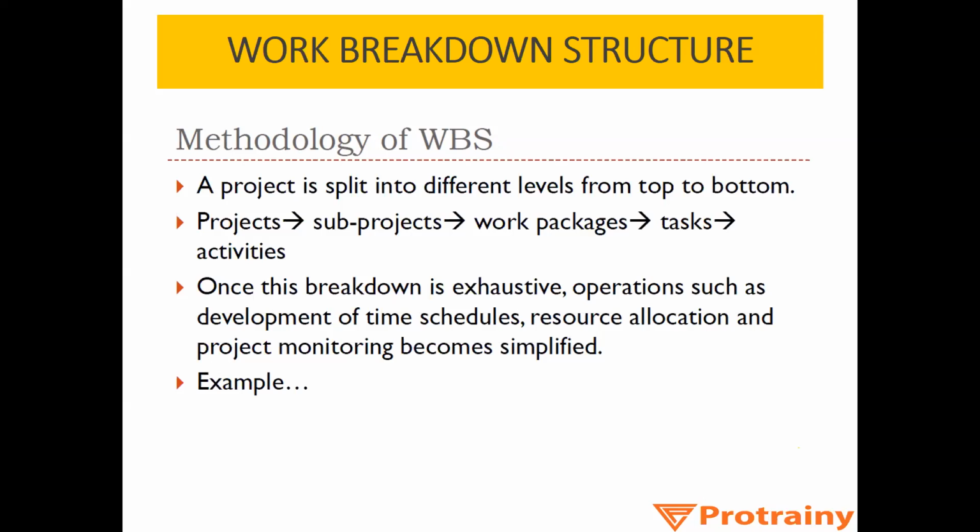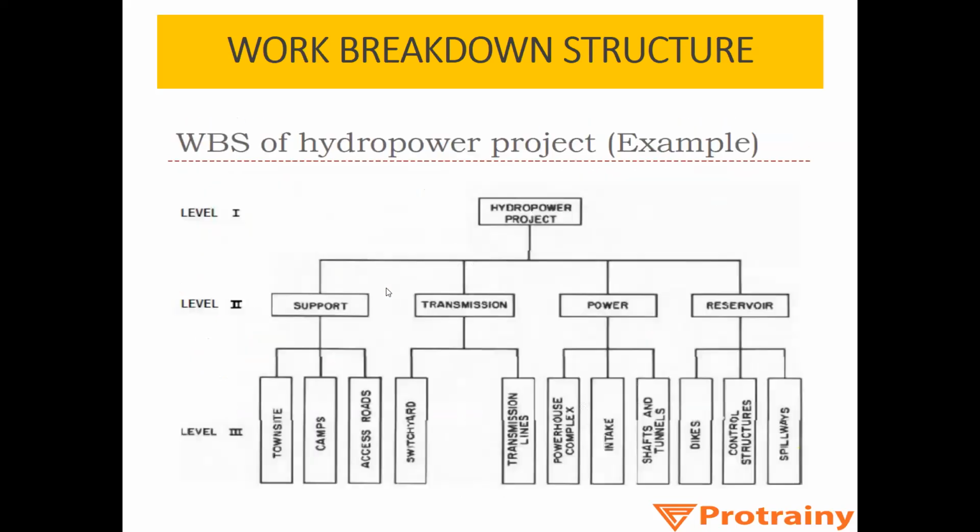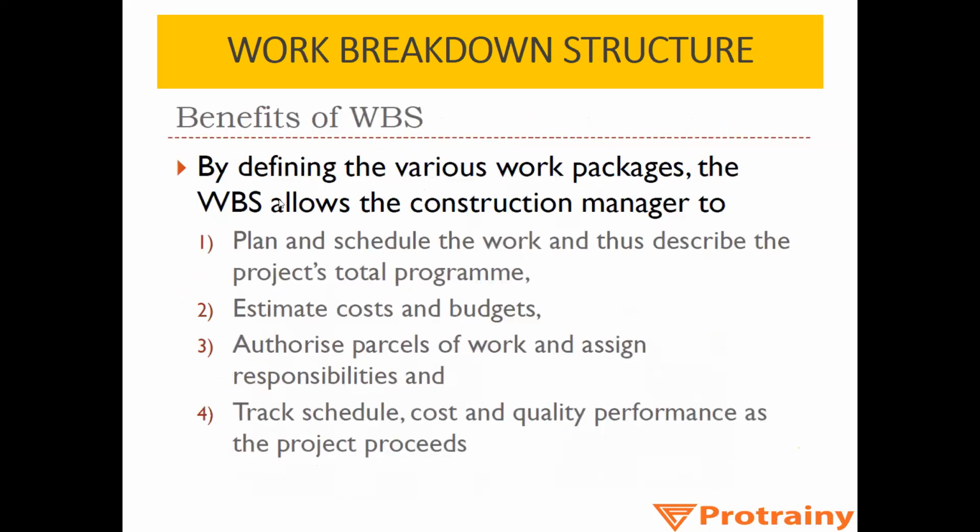Now in substructure, you will further divide into other activities like excavation, raft footing foundation, then basement slab, all these things. So you keep on dividing the activities into sub projects, work packages, tasks, and tasks into activities. Once this breakdown is exhaustive, operations such as development of time schedules, resource allocation, and project monitoring become simplified. We are going to study 2-3 examples. Before that, I'll just complete the theoretical part.